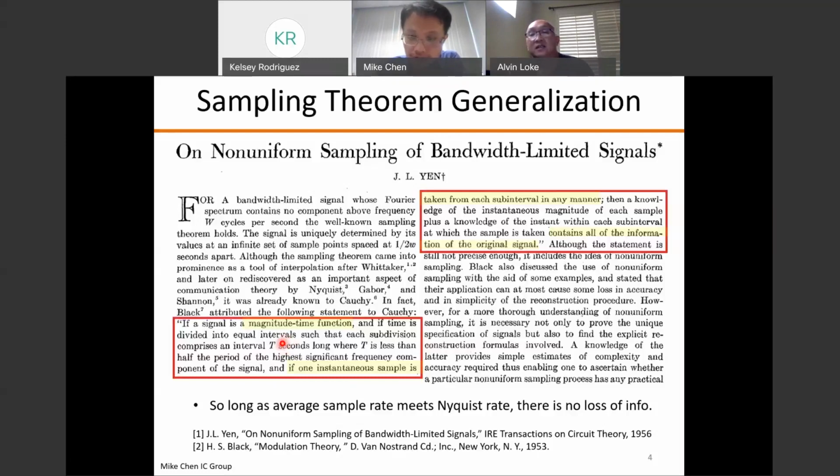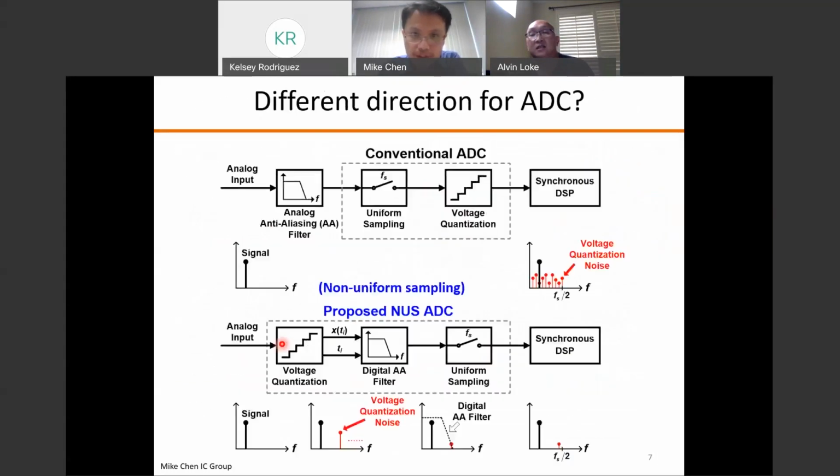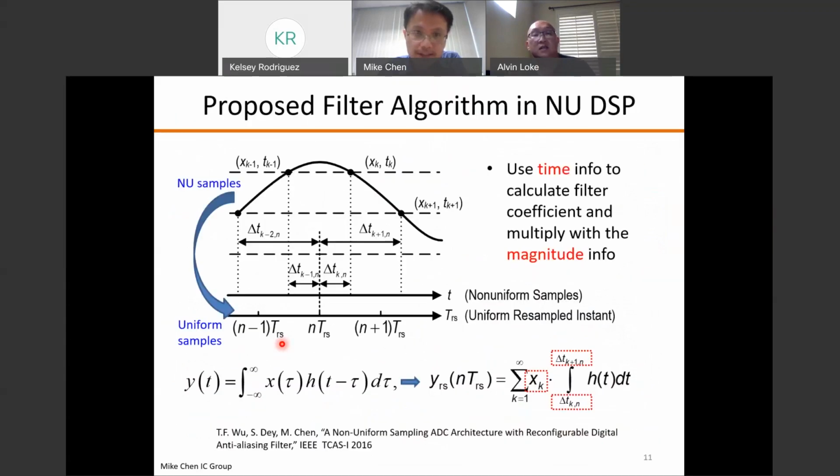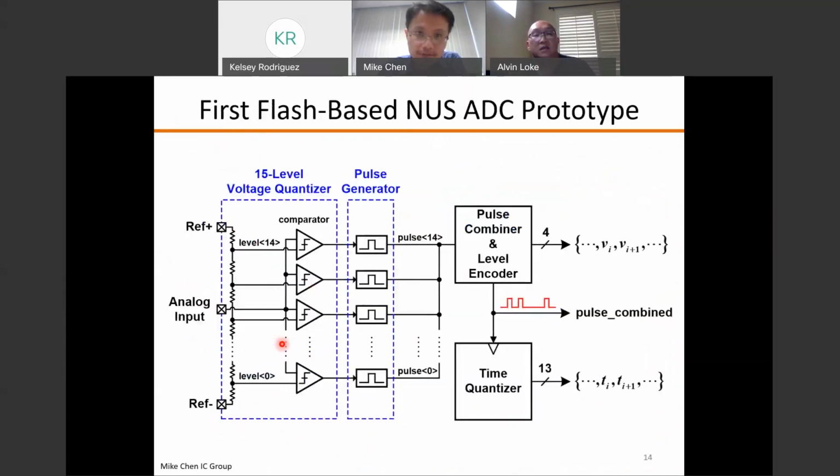Yeah, so that's a pretty good question. There are a couple of things. If you are using this signal-dependent sampling, as you can see here, we always generate a pulse whenever the signal crosses a certain level. So those times are exactly signal dependent. Whenever I cross the level, I just generate a sample event, so there's nothing that we can control; it's really generated by the input.